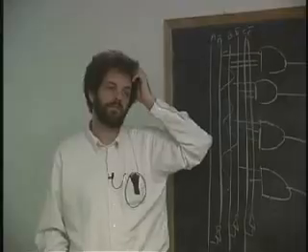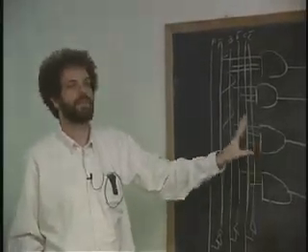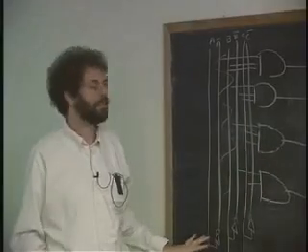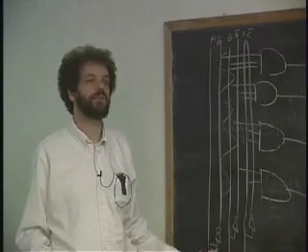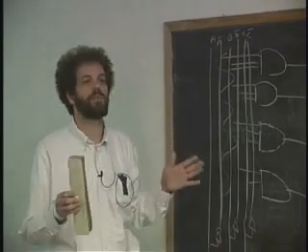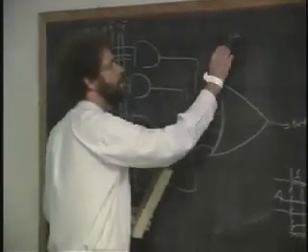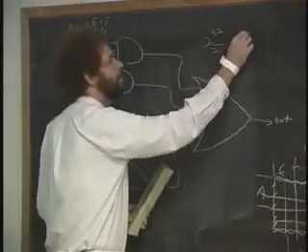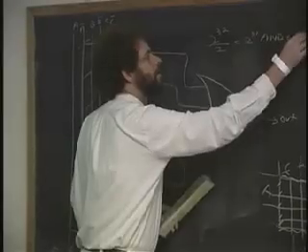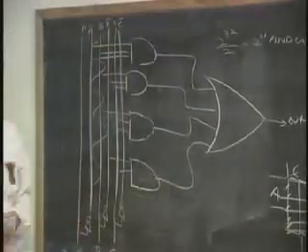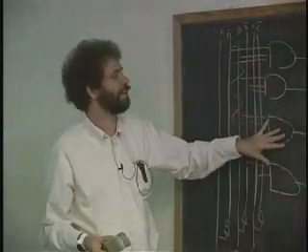Okay, and that's awful. It turns out that this is an exponential growth in the complexity of the circuit versus the number of inputs to do parity. And that sucks, because often we want to take the parity of a 32-bit word. And God forbid we should have a 32-bit word with 2 to the 32 over 2 equals 2 to the 31 AND gates. First of all, that is 2 billion AND gates. Now, integrated circuits are nice, but 2 billion AND gates is still a whole lot of AND gates.